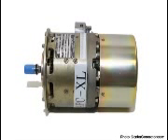The rate of cutting is reduced. When the loop is vertical, no lines of force are cut since the wires are momentarily traveling parallel to the magnetic lines of force, and there is no induced voltage. As the rotation of the loop continues, the number of lines of force cut increases until the loop has rotated an additional 90 degrees to a horizontal plane. As shown in Figure 9:3, the number of lines of force cut and the induced voltage once again are maximum.